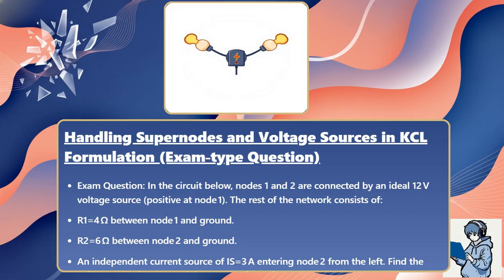Exam question: in the circuit below, nodes 1 and 2 are connected by an ideal 12-volt voltage source, positive at node 1. The rest of the network consists of resistor 1 equals 4 ohms between node 1 and ground, resistor 2 equals 6 ohms between node 2 and ground, and an independent current source of 3 amperes entering node 2 from the left. Find the voltage at node 1, V1, and the current through resistor 1.